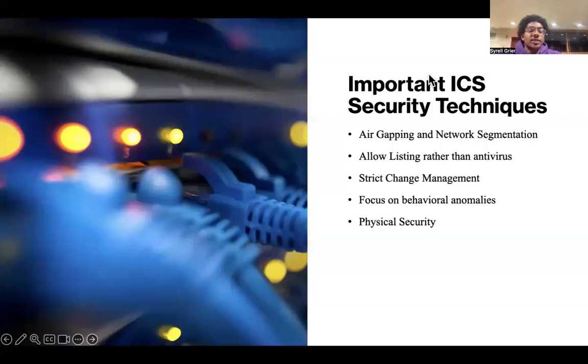The third technique is strict change management, which essentially means that all changes to hardware, software, or system configurations go through a formal process of review, testing, and approval. This is important because ICS systems are delicate, so an untested software patch or update could shut down a factory or damage equipment. Furthermore, many systems are high availability, meaning that downtime is incredibly expensive or potentially dangerous.